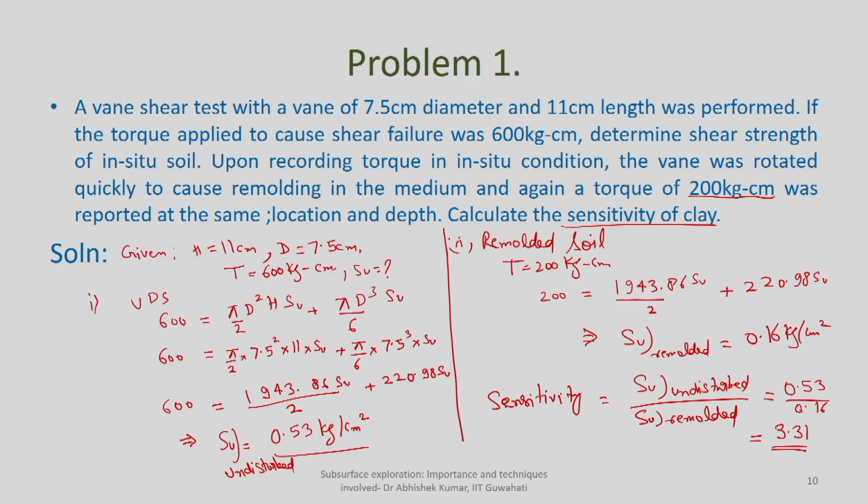Now this is about the vane shear test setup. In the same way, depending upon the depth, you will be able to determine how much the shear strength properties will be at different depths, which you generally get from C and phi values, and the sensitivity of the clay. So keep on doing the same test at different depths, and just like a bore log, you will be able to get the value of the shear strength property at different depths. This is about the vane shear test.